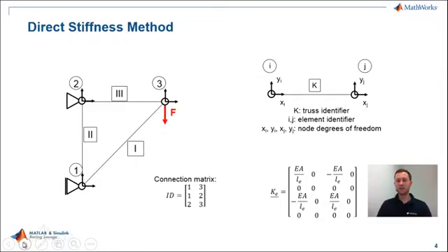As promised, some brief information about the direct stiffness method. I will do that with a very easy truss framework. You can see it at the left, just 3 truss elements, or some call it beam elements. In that case, a truss, you can imagine that as a spring, just a spring with a longitudinal stiffness. That's the easiest approach using the direct stiffness method, but it's already containing all the methodology. So let's have a look here.